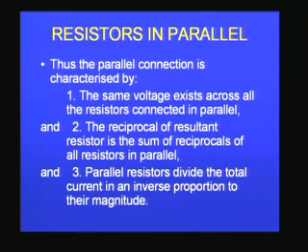Now, let us summarize the various important points that we should remember when we have resistors connected in parallel. The same voltage exists across all the resistors connected in parallel. That is one important point that you have seen already. And the reciprocal of the resultant resistance is the sum of the reciprocals of all the resistors individually taken, in the case of parallel resistors. And the last point is parallel resistors divide the total current in inverse proportion to their magnitude. Larger resistor provides less current, smaller resistor provides larger current.